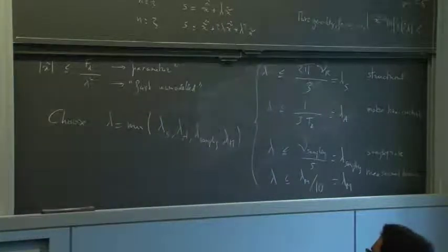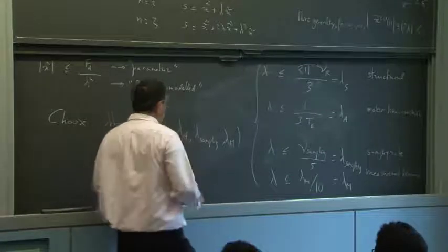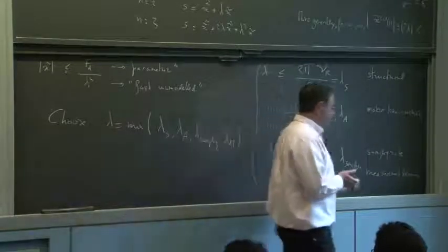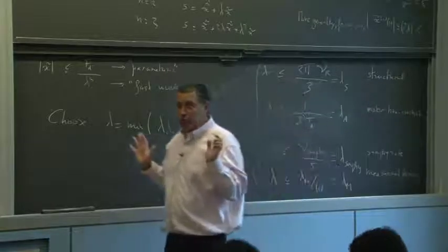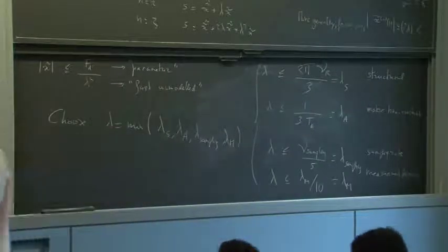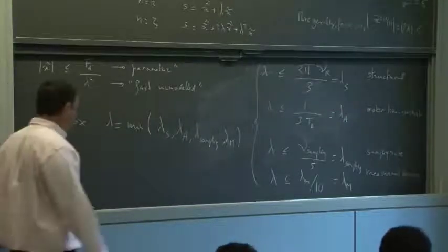Because this has to be as large as possible and still smaller than all. So that's what you would do. By the way, it's exactly what you would do for a linear system as well, except that for a linear system you could be more precise about all these bounds because you can play with root locus, or just explicit eigenvalues.